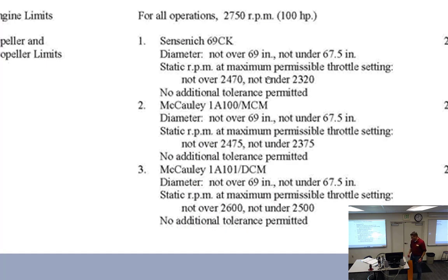And then he undoes it and takes it over to the prop bench. He puts a little protractor on it. Yeah, it's just going to need another half degree on there. And he brings it back in, does the same thing, just pulls it. Yeah, that looks pretty good. And he does it to the other side, prop checks, and goes, you're good. And he just repitched the whole thing, like right there. I'm like, perfect. Damn, man. All in the span of like just a couple minutes? Yeah.